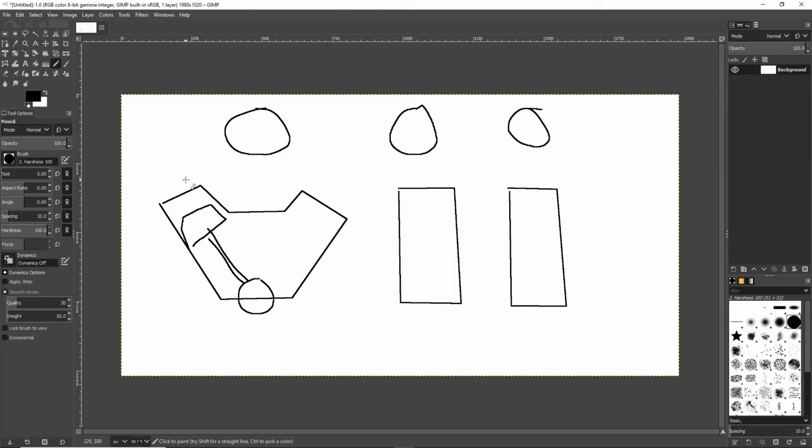But how do we get these valves to open and close, right? We've got an intake and exhaust valve. How do we get those to open and close? We need a camshaft. On a pushrod engine, you would put the camshaft right here in the block, and we put a chain or a belt or some gears. Terrible drawing. And then pushrods, which would come up like this through the head, a rocker arm, and in this way, when this lobe pushed the pushrod, it would open this valve.